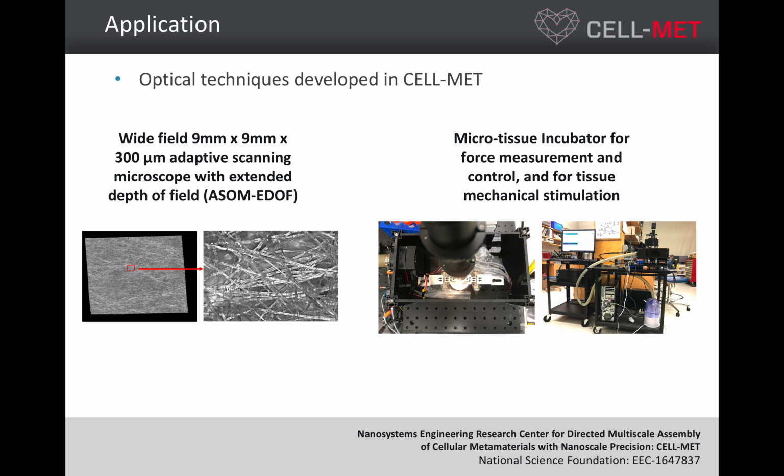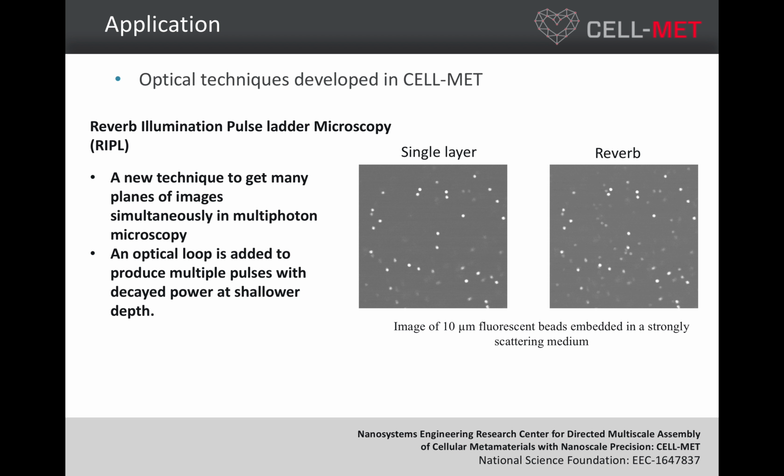And the second thing is that we just designed these tiny fixtures which can clamp down onto the PDMS wells, which contain the micro tissues, and through these fixtures we can either pull in or pull out, or stretch, those PDMS substrates. And when you stretch these wells, the microstructure inside the wells can also be stretched. So that's the way we give force to the micro tissues and do force measurement at the same time.